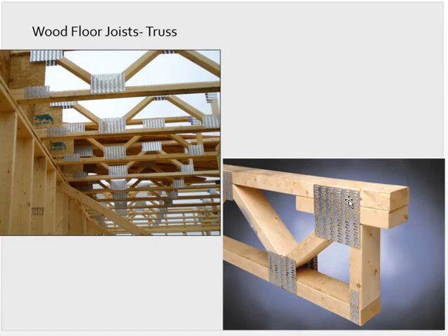These are designed by the truss manufacturer. The structural engineer or the architect would provide the information to the truss manufacturer who actually designs these, provided a lot of different varying information that they need, and then it's brought to the job site, custom built just for this. And the point I was getting at is that they should never be cut or altered.